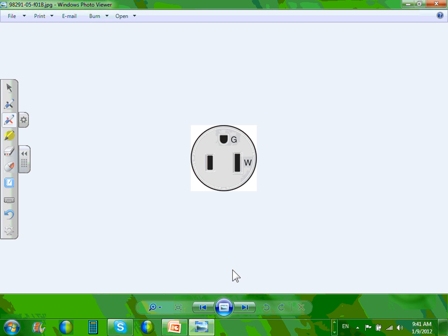Okay, this is just identification of the switches that we talked about, guys. Different types. Look at this one. You have to memorize it as a project manager because you walk around. If you ask the inspector for a 20 amp receptacle and they put this receptacle in for you, that's clearly a 15 amp receptacle. So remember this, guys. This is the most common, convenient commercial receptacle that you're going to install: 20 amp, 120 receptacle with that little slide to it. Obviously, the one before it was the 15 amp.